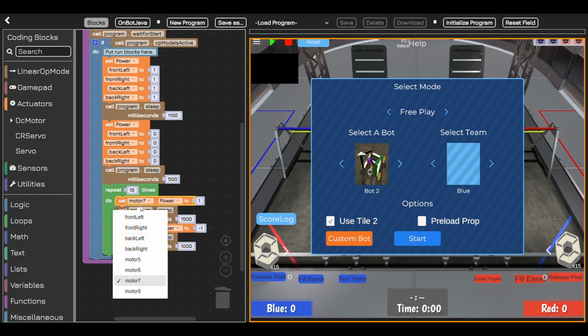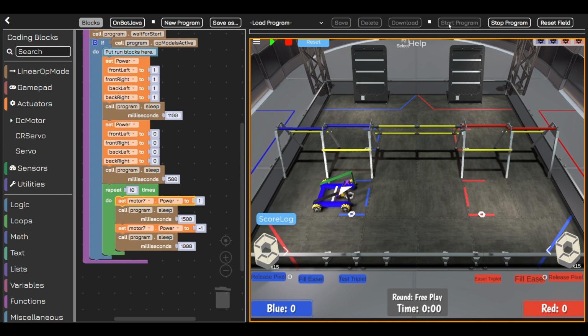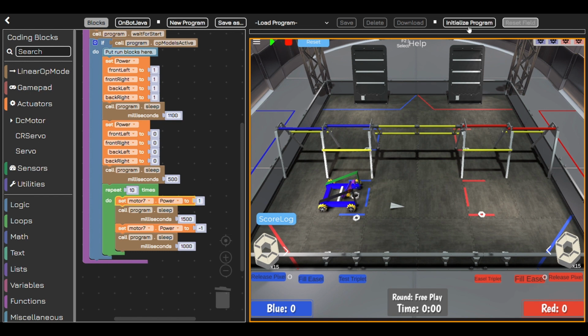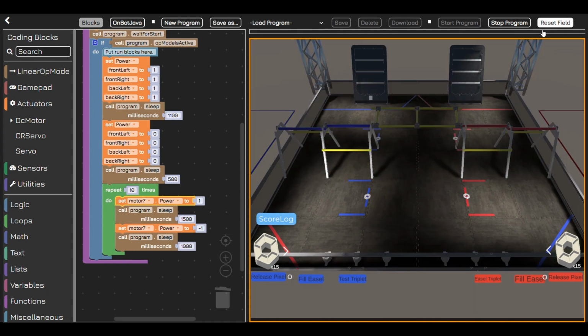Finally, the motor power is quickly switched to 1, which throws the plane forward for the duration specified by adjust time. In summary, Motor 7 first tilts the launcher backwards to load the plane, then forward to throw it. The adjust time value controls how far back the mechanism is pulled before being released. Similar to a slingshot, with the proper adjust time set, the plane can be launched at varying speeds and power. Mastering these parameters allows the bot to accurately control the flight trajectory.